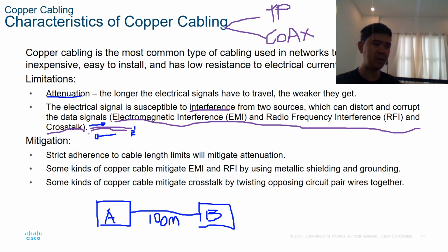What I mean by ample distance, for example, if you look into electrical standards, if you have a group of network cables in the ceiling, it should not be near the electrical cables. There is an ample distance in meters between the network cable pipe, the group of network cables, and our electrical cables, and this helps to lessen the interference.